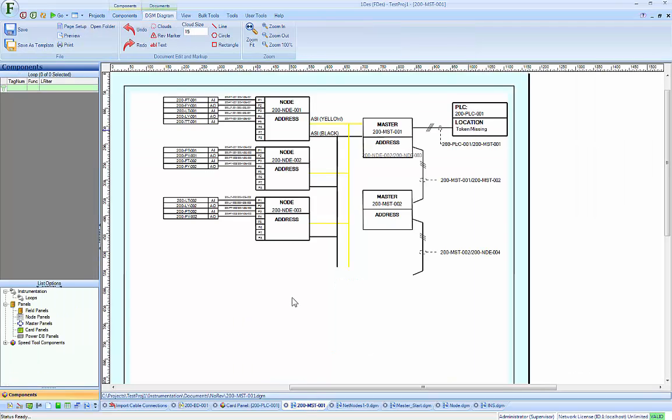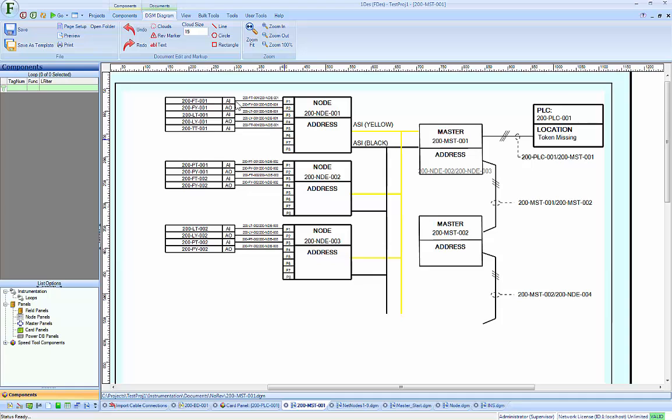The net layout document type is a cable connections only document type. That means that there is no detailed connections necessary for this to work. If I want to, however, I can go and add each instrument to a specific port onto these nodes.